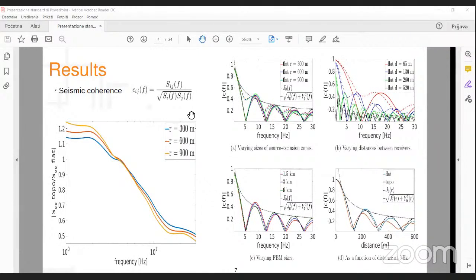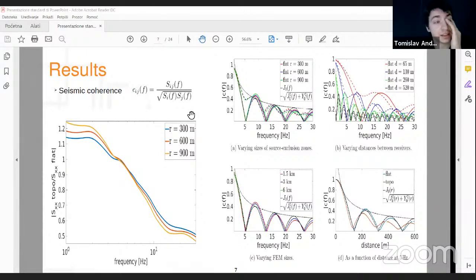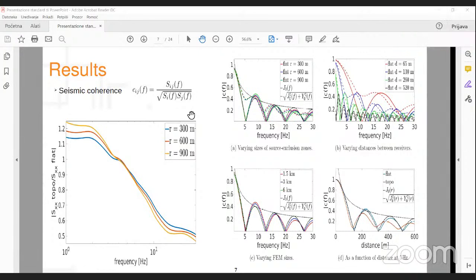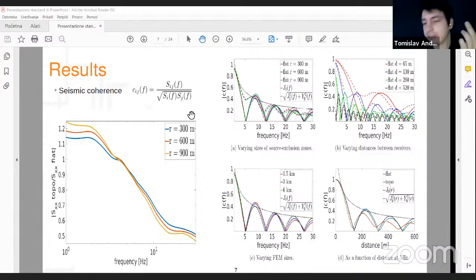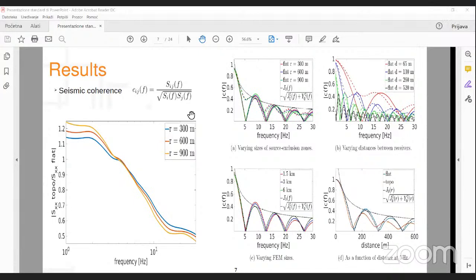So how do you do the CPML? It's basically implemented in SPECFEM3D. It's intrinsically there. So what are your inputs for the PML? You just need to define how many layers, or what is the thickness of the CPML. Okay, so only the thickness matters. Okay, cool.